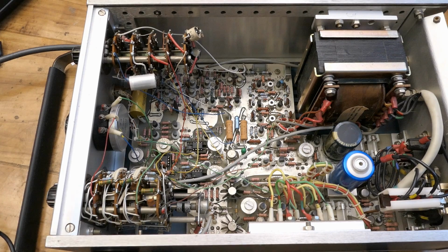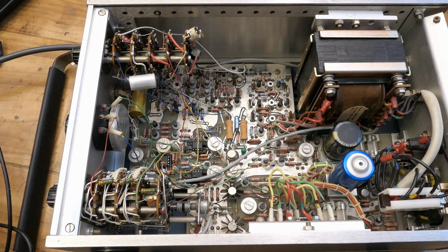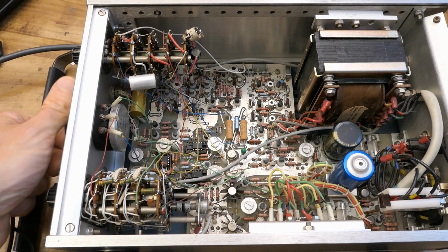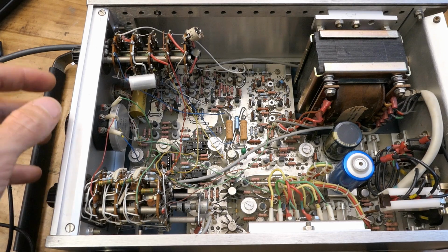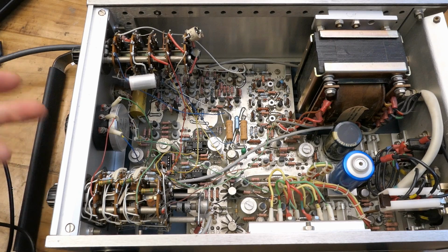Of course the non-symmetrical waveform in one half of the range of this potentiometer made me think there is some problem in the potentiometer, but I was thinking it's a double potentiometer with one section not making contact in the lower half or something, but this is just a single potentiometer, not a double one, not two potentiometers on one shaft. So I don't really see this potentiometer causing the problem.